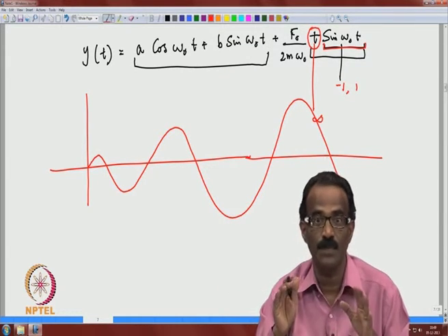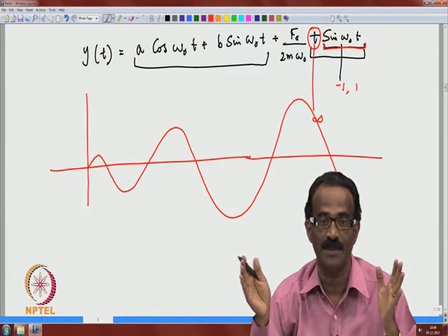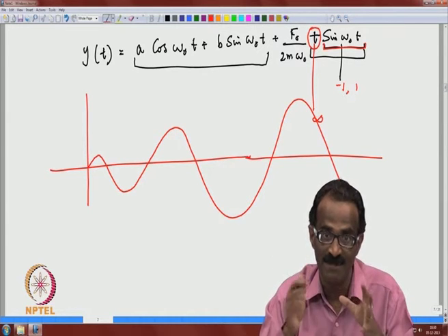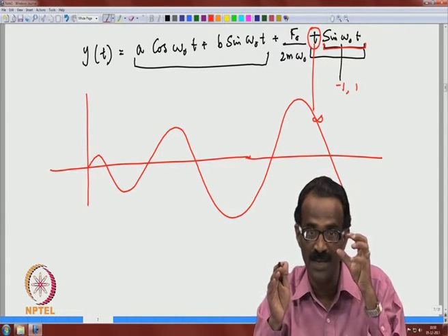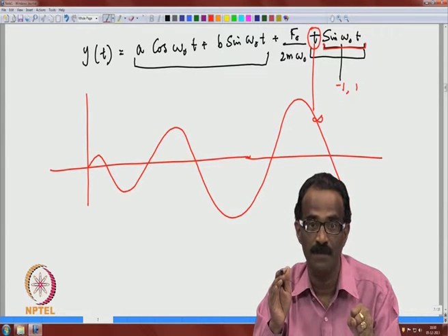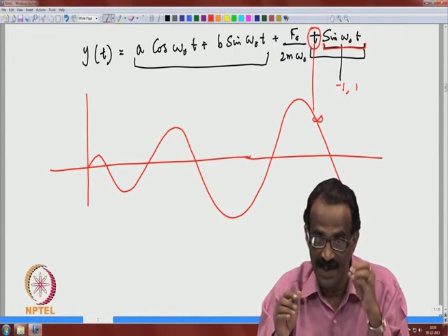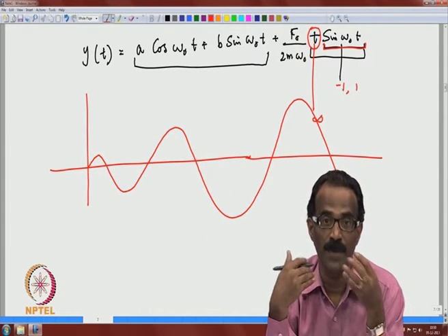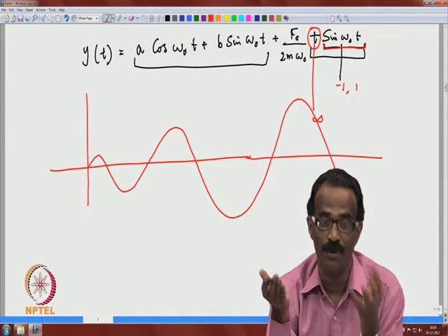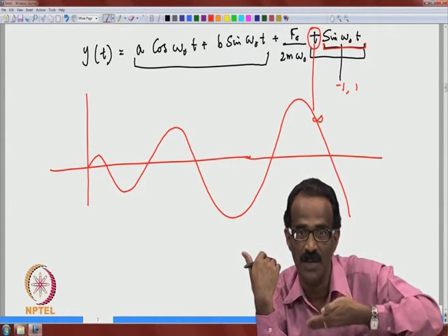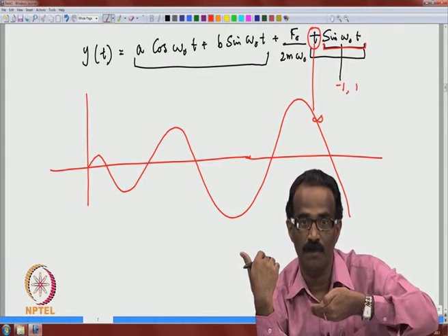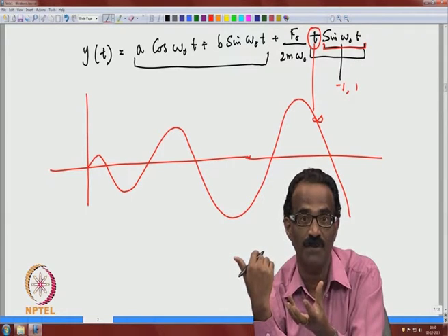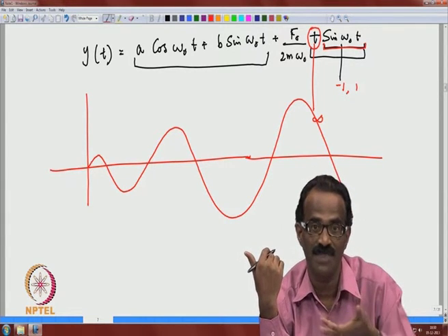This is what you have to take into account when you design any mechanical system like a bridge. You have to put enough damping in the system, because the external frequency may not be under your control. For example, there will be a lot of vehicles traveling through your bridge, and they will automatically create their own external frequency, while your system has a certain frequency.